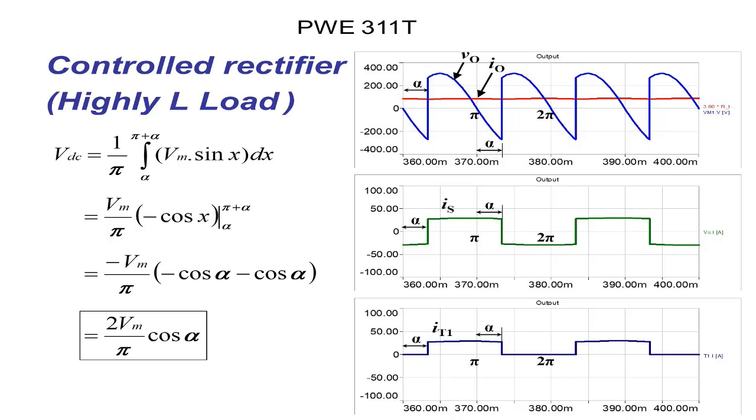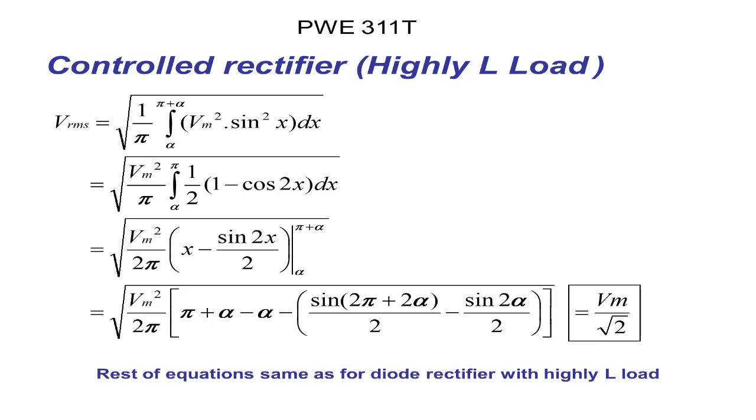And you can see how the source current, Is, is not sinusoidal anymore. It contains a lot of harmonics with flat tops. The same thing as with the transistor. So you should know those waveforms.